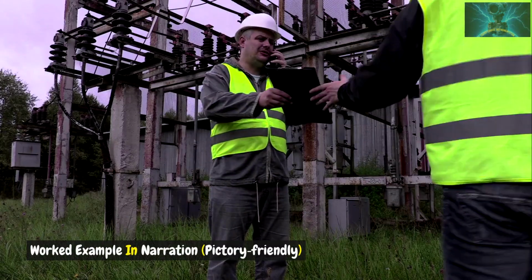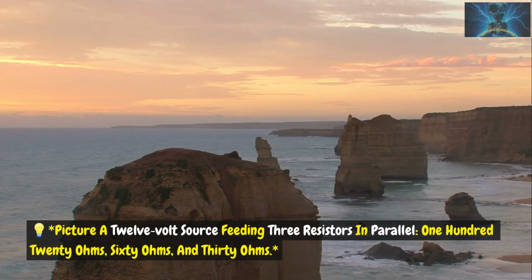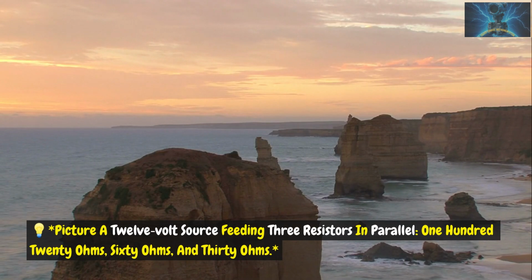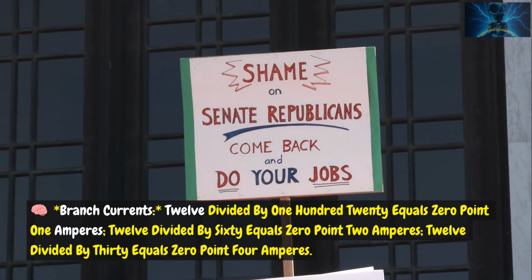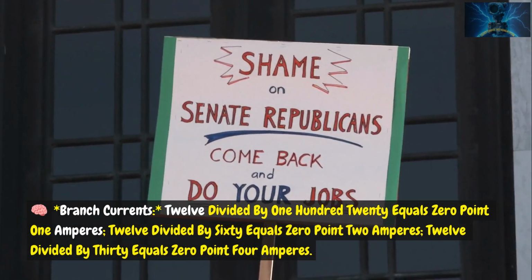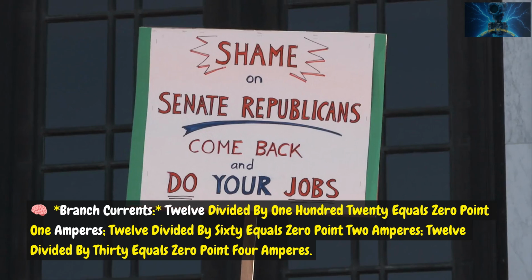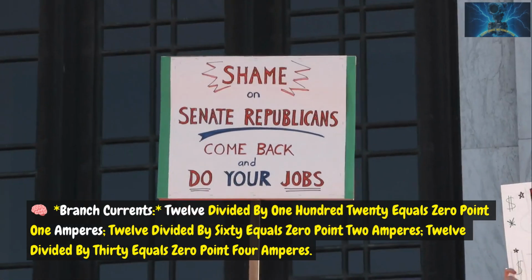Worked example in narration. Picture a 12-volt source feeding three resistors in parallel: 120 ohms, 60 ohms, and 30 ohms. Branch currents. 12 divided by 120 equals 0.1 amperes. 12 divided by 60 equals 0.2 amperes. 12 divided by 30 equals 0.4 amperes.